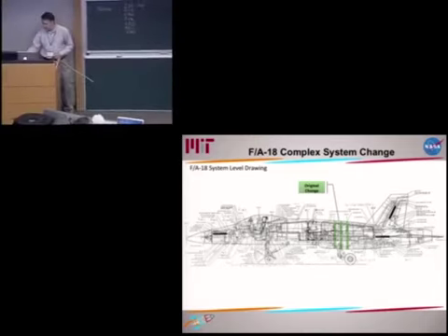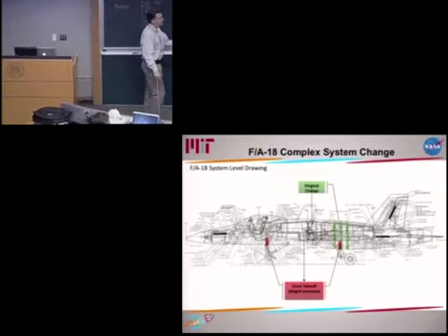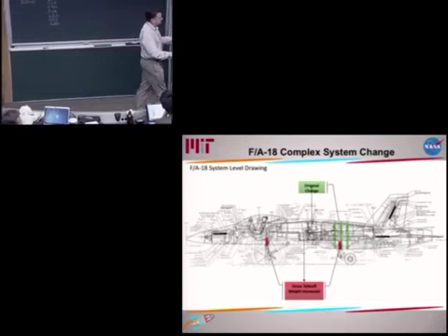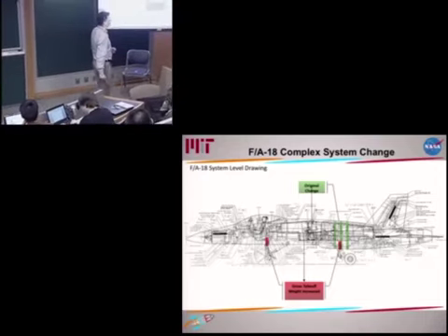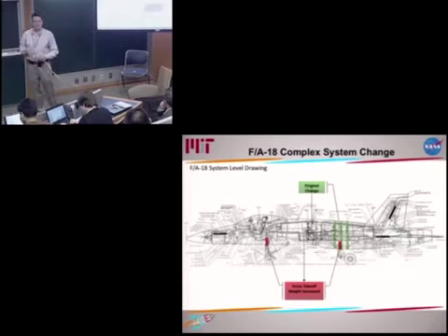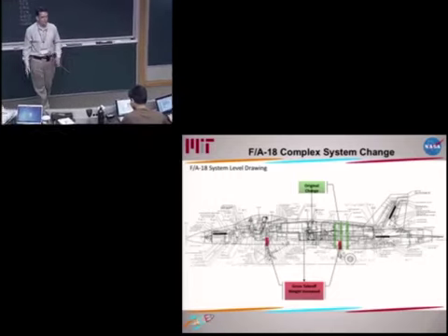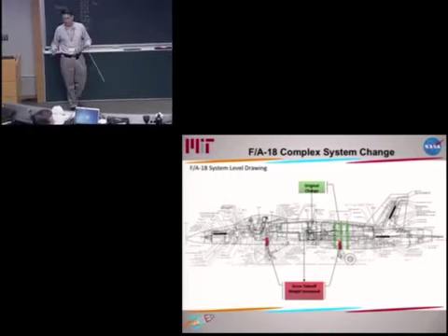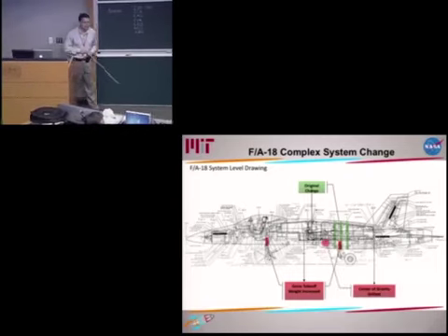The problem is that, as you can see, this is a complex system. So by making that change, now there's some other, and I'm showing this in green because it was a good thing, because it gave us what we wanted, better fatigue life, but then other things happened. Gross takeoff weight, so gross takeoff weight means the weight of the aircraft with the passenger, with the fuel, everything included, was increased, and that leads to a decrease in range.